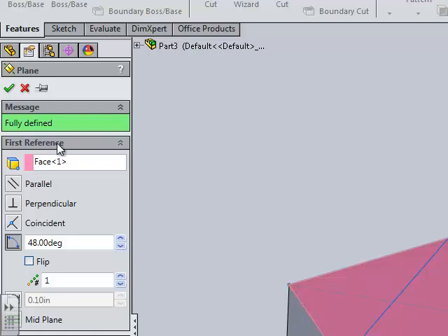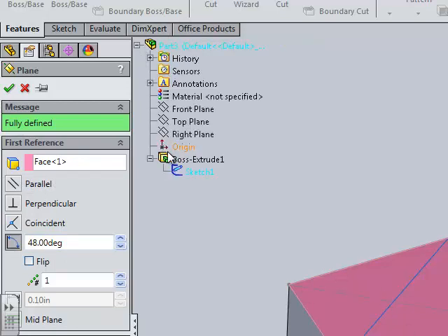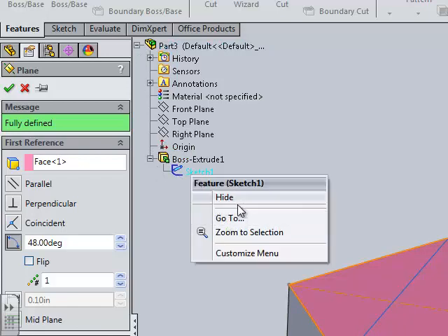Again, now you have the option of making it blind, so it's going one direction, or midplane, or center, keeping the line at center for our second. I recommend doing midplane. Then I change the angle, because once we have the circles, it'll be much easier to place them. Select 52, go midplane, one direction, 12 millimeters. Then click into your sketch, right-click, and show it.